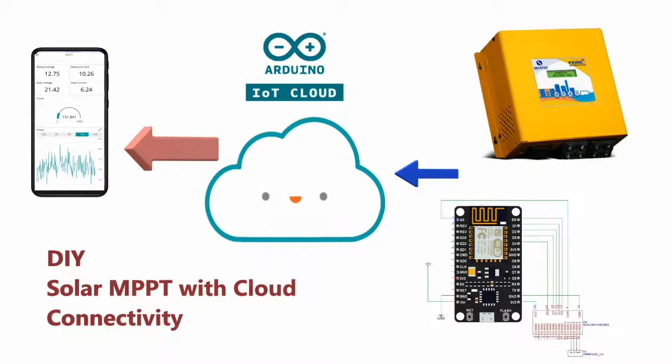For this, I connected a variable power supply to the solar input of the MPPT, adjusted the voltages and measured the voltage across the divider network. With that I was able to find out by what factor the actual voltage is reduced before going to the ADC of the microcontroller.